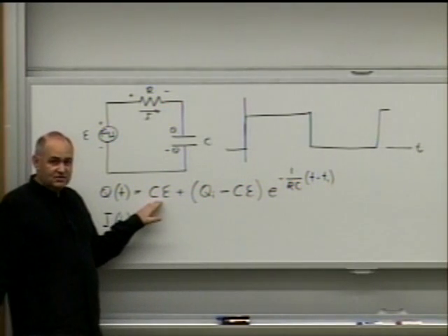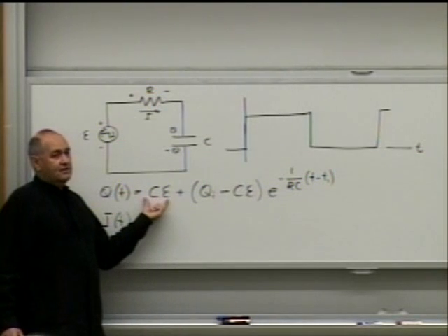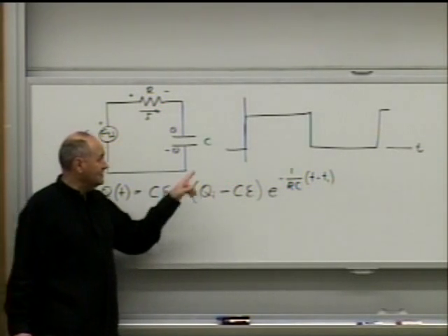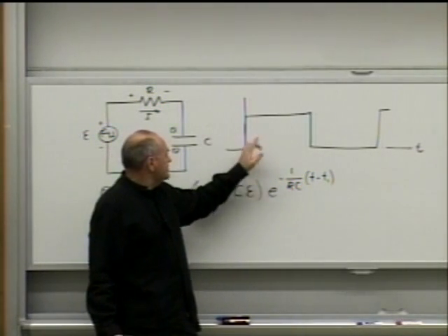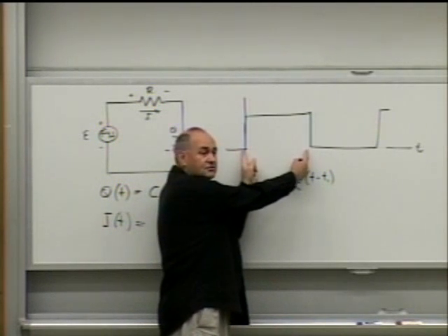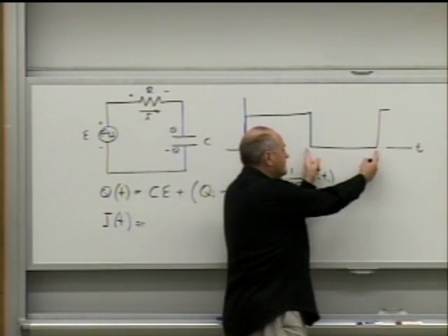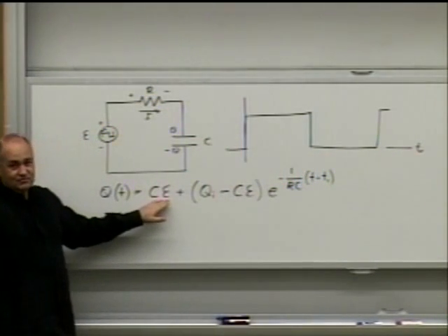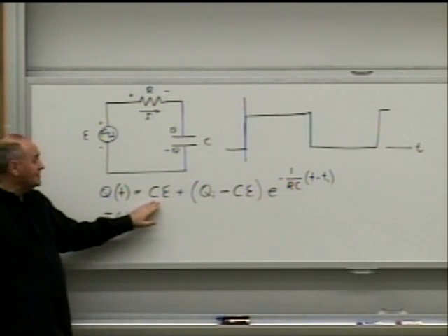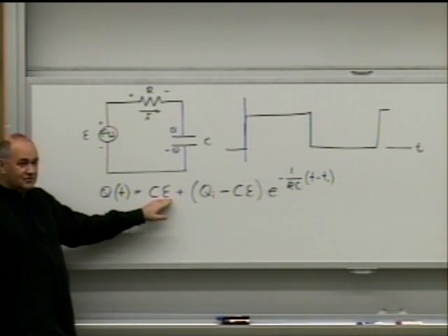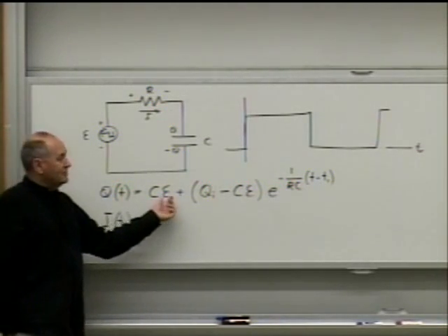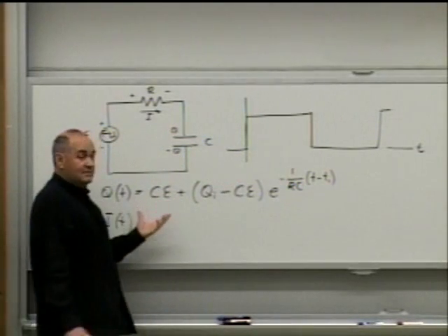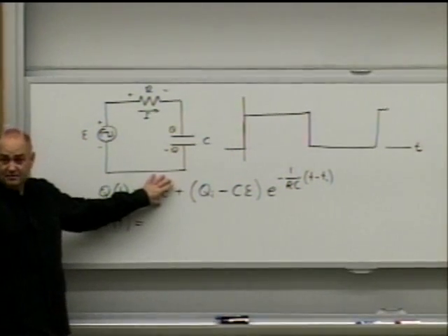So first we have to differentiate this function. And remember that although electromotive force is a function of time, it is a relatively simple function of time. So we are considering only intervals when electromotive force is constant. So really this function is a constant. Capacitance is a constant, and electromotive force is a constant. The only points where electromotive force is not constant are the beginning of those periods. So derivative of a constant is 0. So the first term becomes 0.